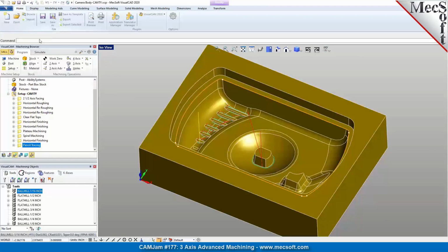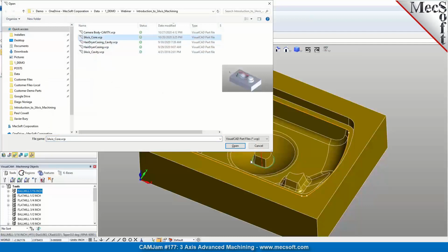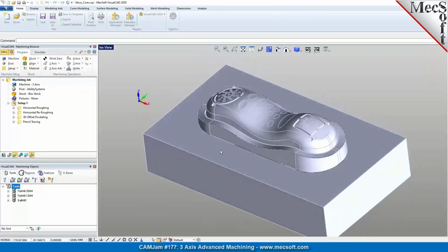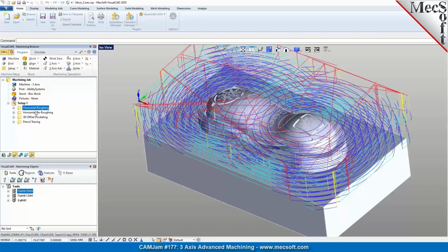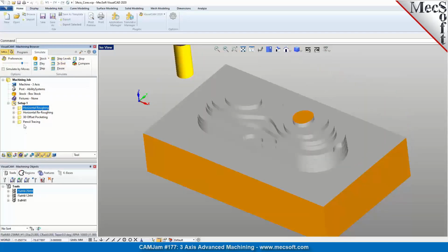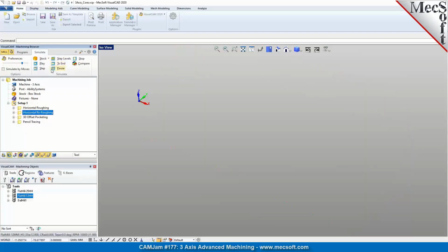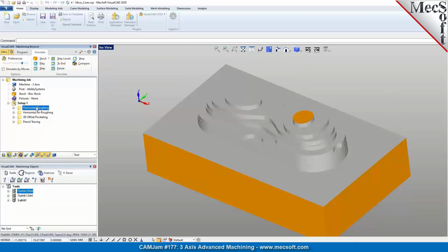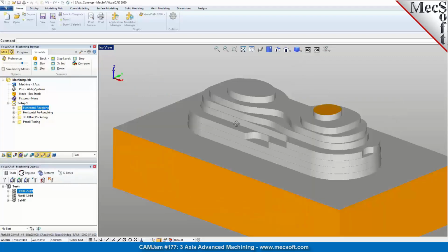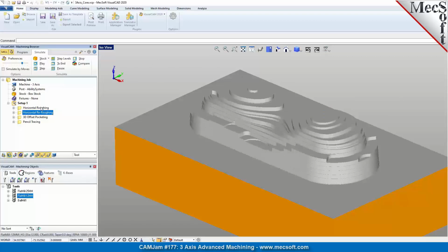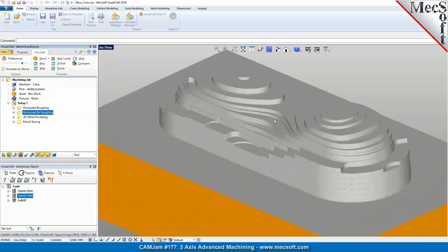I do have one other example in here of a mold core, which I'd like to point out real quick, programmed in Visual CAD/CAM. Similar type of toolpath methods being applied, roughing to start with, a horizontal or Z-level roughing toolpath. Then we have a re-roughing toolpath generated to go back and clean up the areas that were unable to be roughed out using the large cutter. So you can see that the re-roughing brings it closer to the net shape of your part.